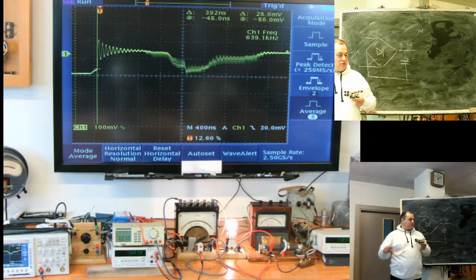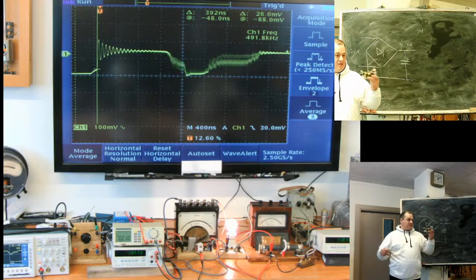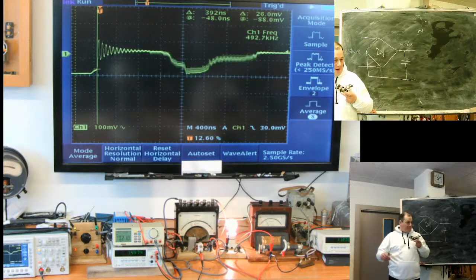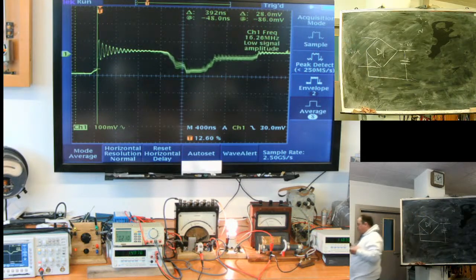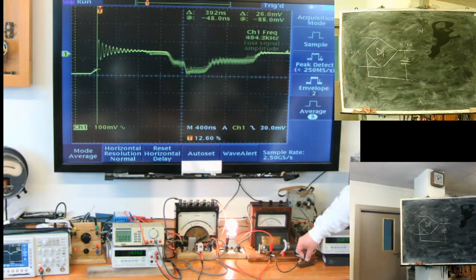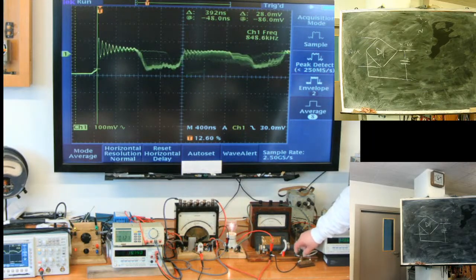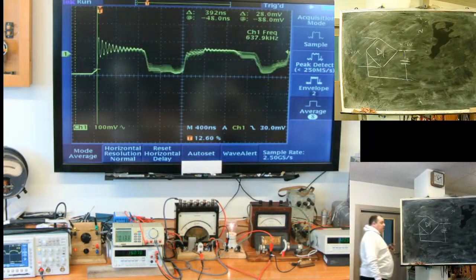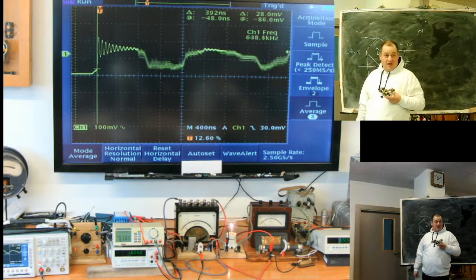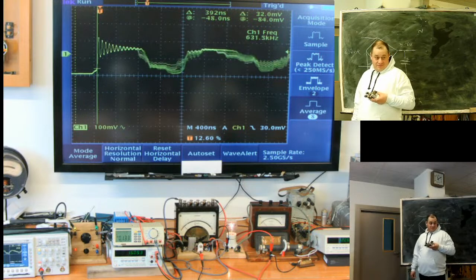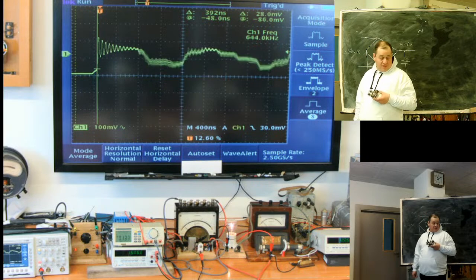A step down converter cannot supply voltage above its input. Step up converters use the self-inductance of a coil. Also, such a controller can be voltage inverting. It can convert 24 to -5. Yes, there are. PWM-based power controllers can also invert voltage.